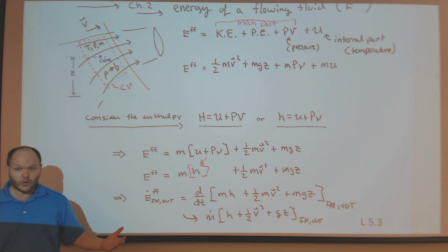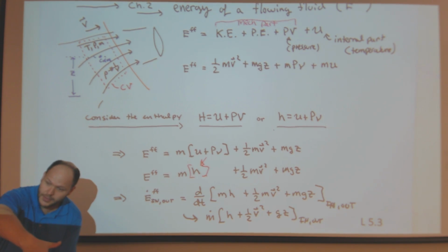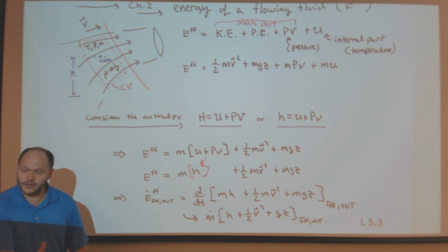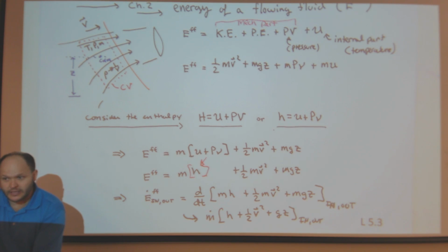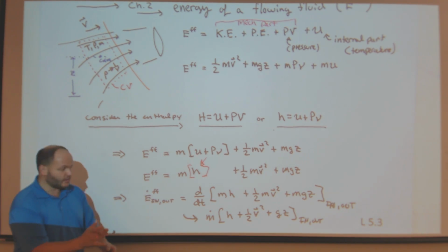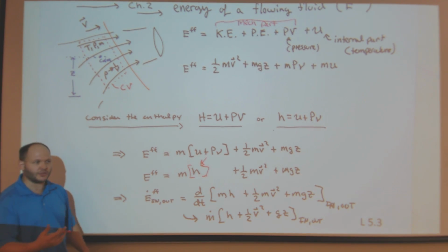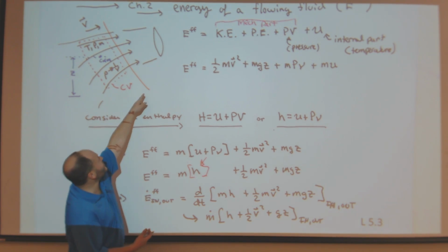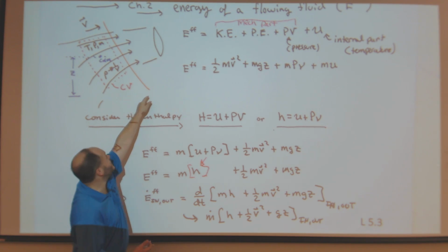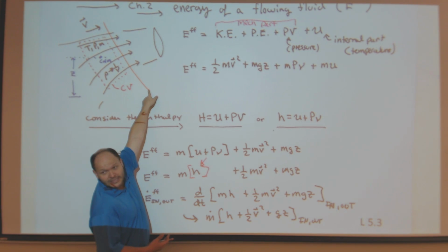Now, in a turbine or a pump working at steady state, that's exactly what happens. I have my inlet to my pump, and I have mass coming in at constant velocity. There's a mass flow rate in. The temperature of the inlet isn't changing. The pressure isn't changing. So this is just a way of writing it. It takes a while. You have to think about it some more. It's not intuitive. You have to think about the control volume, about this thing crossing a boundary, another boundary. This is my control volume, my fluid coming in. This is my boundary to my system.